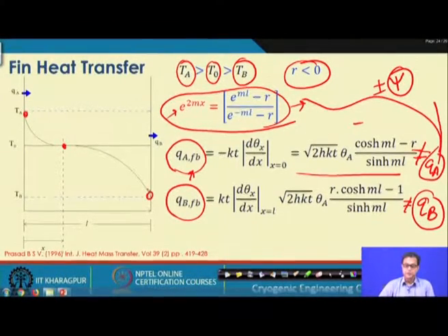So while analyzing plate fin type heat exchangers, when there would be multiple fluid streams arranged in multiple layers, we cannot separately keep notice whether there is transverse conduction or not, because it is not possible to know what is happening between the plate and the fluid temperatures at some intermediate location. So automatically the equations should be framed in such a way that the effect is taken care of.